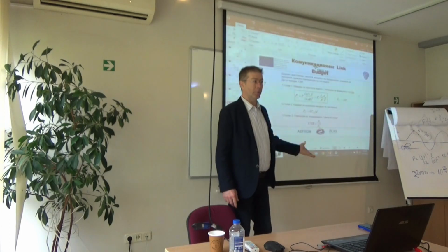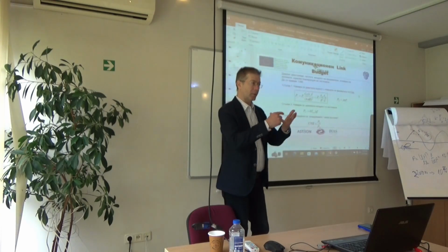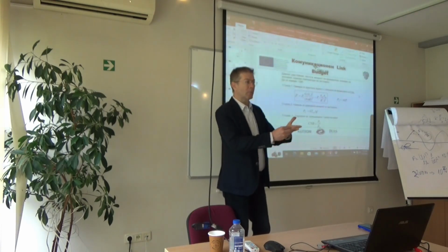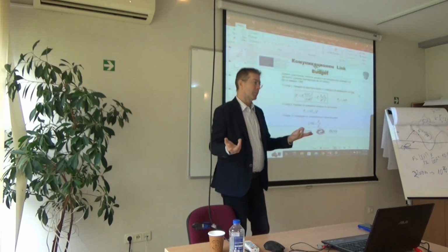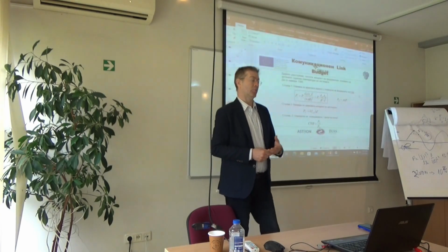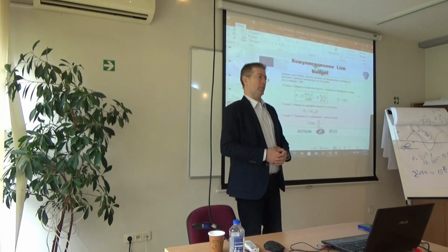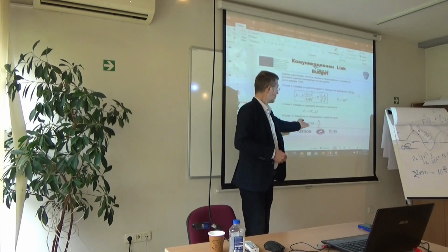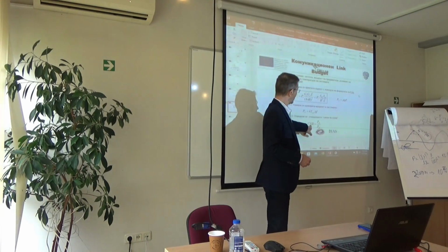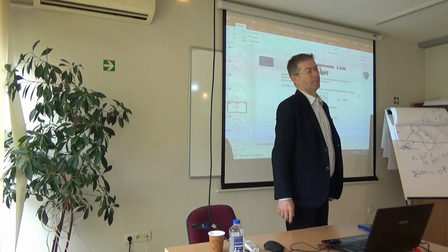It is the power of the useful signal divided by the power of noises generated in the antenna, received through the pattern, or generated in the active devices of the receiver. Usually the first stage of the amplifier is the essential contributor to the noise of the receiver. C2N, C over N, different ways to say carrier to noise.